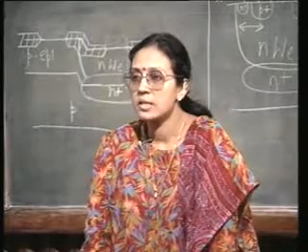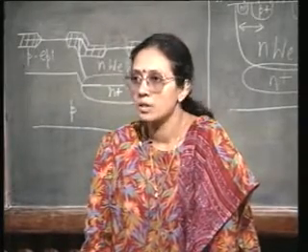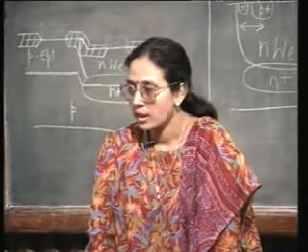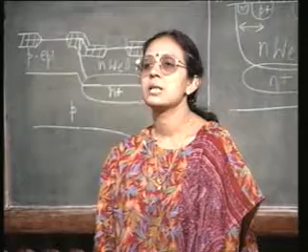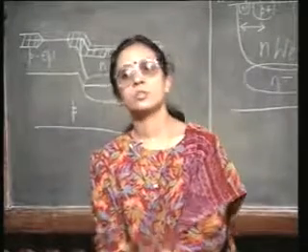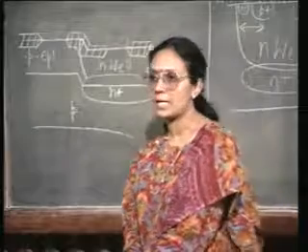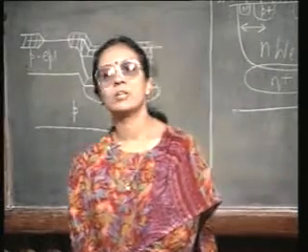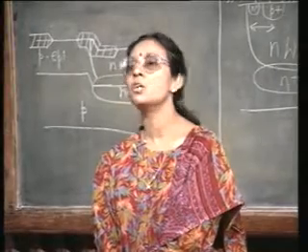And for an ECL transistor we use the poly emitter, poly extrinsic base transistors. So, suppose I could put in ECL logic in those bottlenecks, and the rest of the portions where I do not need that high speed, I do with CMOS, where I can realize very high packing density and very low power dissipation.